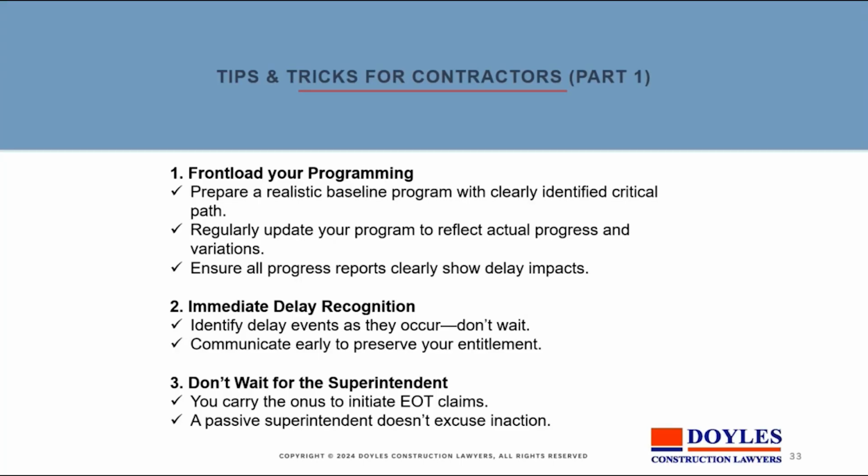The other aspect is to immediately recognise delays. Sometimes delays go on for weeks or days or months, but then somebody realises, hang on, we're not getting ahead on this job because the rock condition is too hard. Understanding delay, recognising delay against your program is very important.